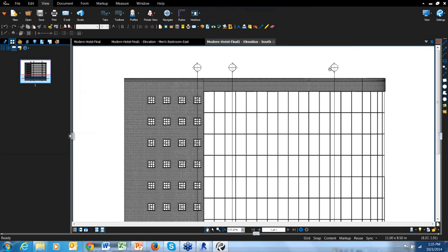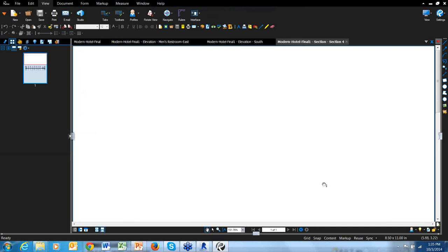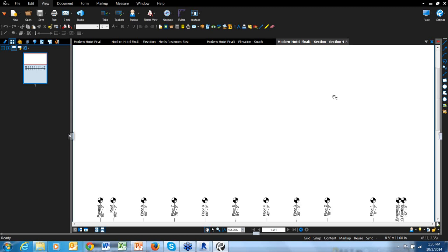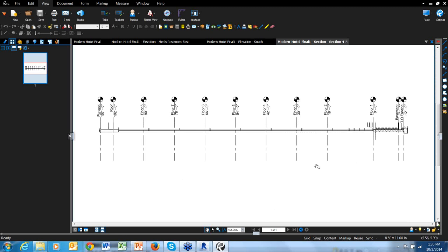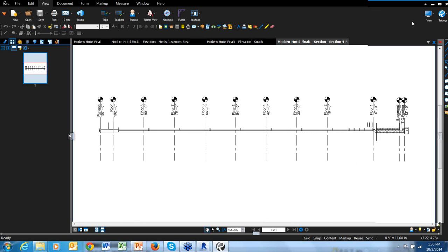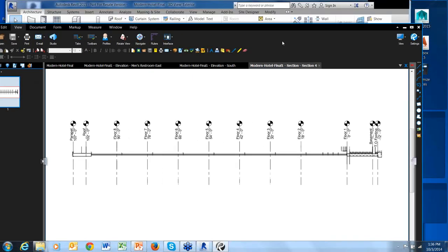I do not have the section currently open, but if I click on that link, the reference in the drawing, it switches to section 4, and there it is. Came in sideways. How cool is that? So you don't even have to have them open, but you do have to print them at the same time. This will not open PDFs that were not printed in the same session of Revit. That is really cool.